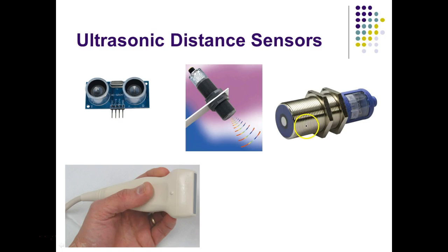These are usually what we call shielded sensors. Notice that the actual outside threads go all the way up to the sensing element itself. We have what we call unshielded, where the actual sensing element sticks out past the threads, and we'll look at that. You'll probably never see an ultrasonic sensor where they want to focus the waves. They don't want things to do what? They want the waves to spread out.